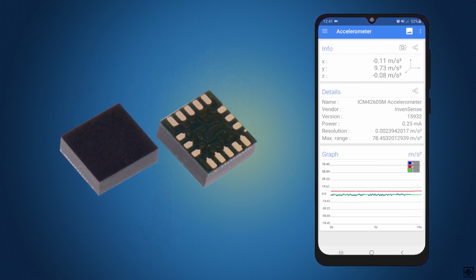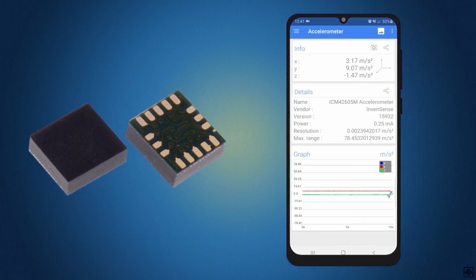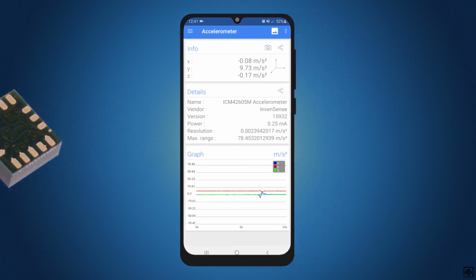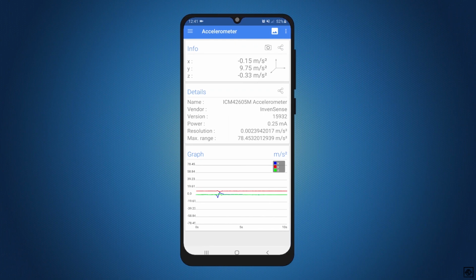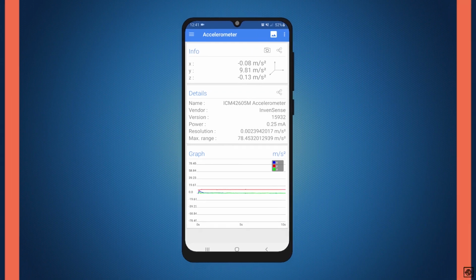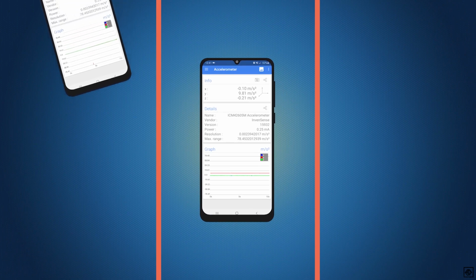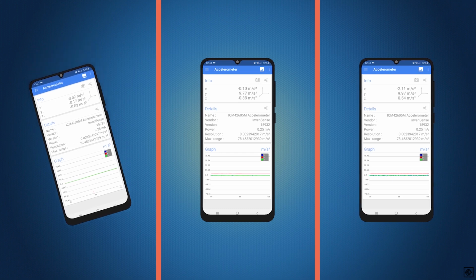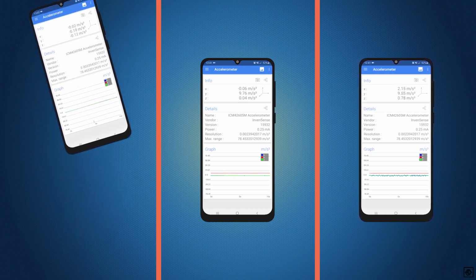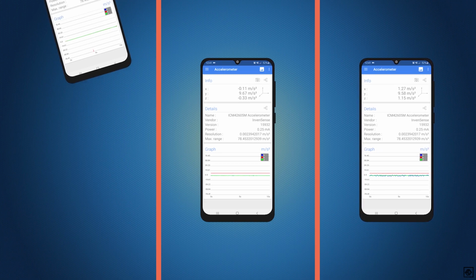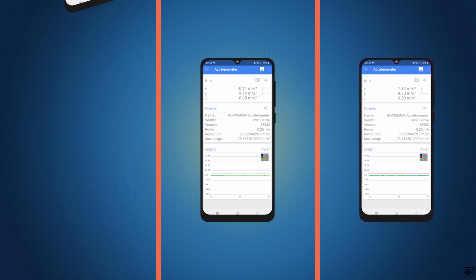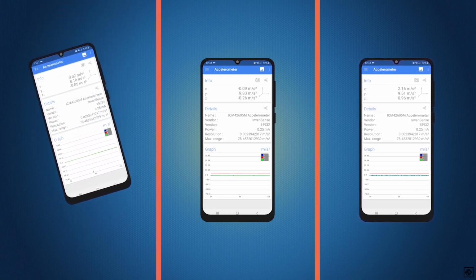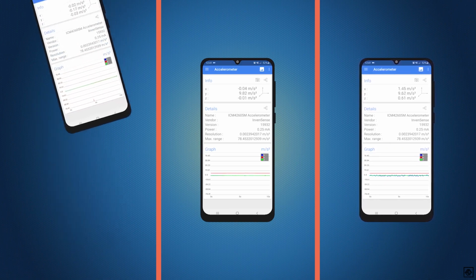The accelerometers detect acceleration over the x, y, and z axis. Now if you move it in any direction, it will detect changes on the axis. So when the phone is at rest or moving at a constant speed, the accelerometer's data is not zero, it's equal to the gravitational acceleration. The accelerometer's output is only zero in free fall. In any other situation, the output of the accelerometer is the gravity vector plus the acceleration vector. So when the phone measures the acceleration in a particular direction, and it's nearby to the acceleration due to gravity, then the phone knows which way is down and thus reorients itself.